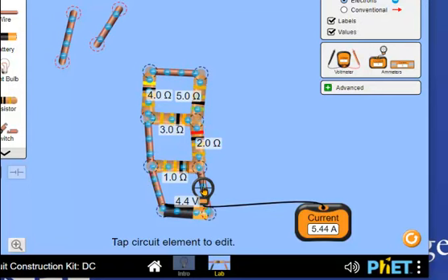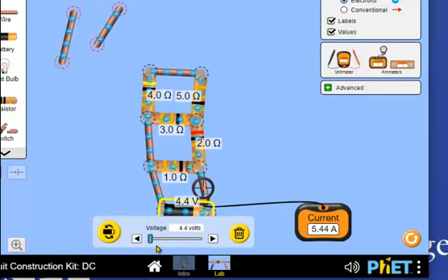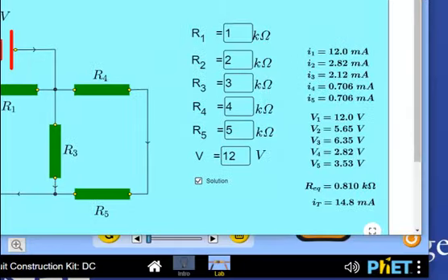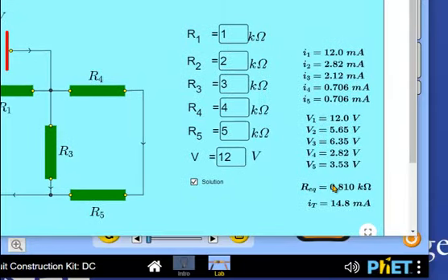And I measure the current. And again, I'm trying to get it down to 5 amps. I'm not sure if I will succeed. Well, actually I will. Yeah, there we go. So I'm trying to get it down to 1 amp. That's good enough. So 0.8 volts divided by 0.99 amps, which is still 0.8 ohms. And that's what it says here, 0.81 ohms.